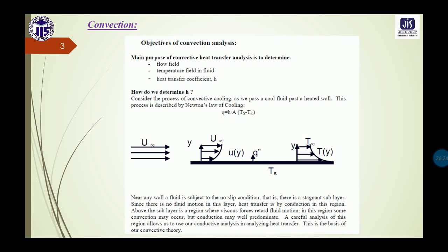Now, from all the different experimental observations, it is seen that a fluid in motion comes to a complete stop at the solid surface, and there it gains zero velocity relative to the surface. That means there is no relative tangential velocity between the fluid and the solid boundary at their contact points.